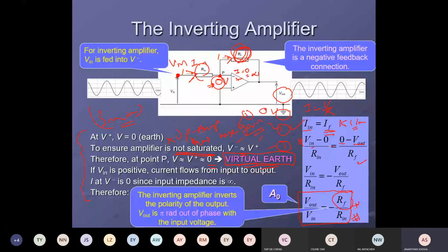In the hall, when someone is talking on the stage and the loudness is not enough, a technician goes and finds the volume knob. Actually, what the technician is doing is just changing one of the resistances of the circuit, most probably the R in.